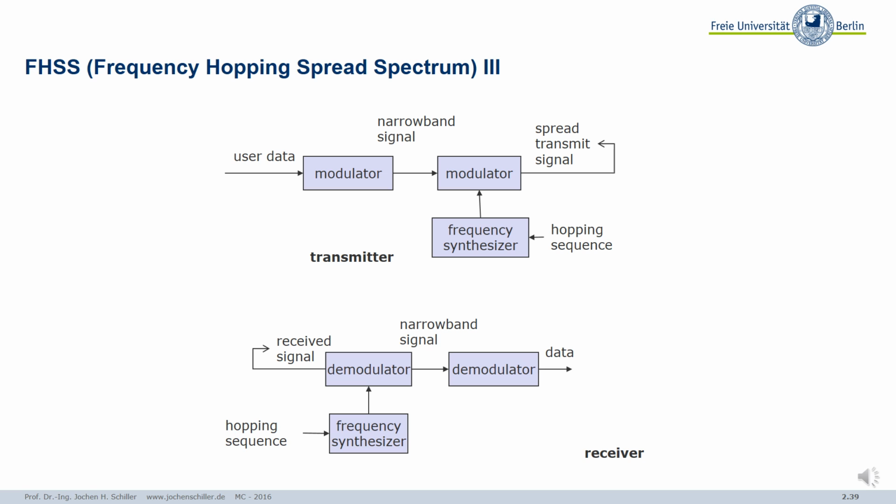And again, that's just this very simple block scheme, how you do this modulation and how you do this hopping sequence, etc. And now the question is, and this is exactly what we learn in Bluetooth, how do we learn the hopping sequence? If you do not know the hopping sequence, that means how you jump through frequencies, it's very difficult to follow someone. Yes, if you receive everything, and you have a signal processor, then you can check basically and you will find out. So it's not something against eavesdropping, but it tries to avoid interference.